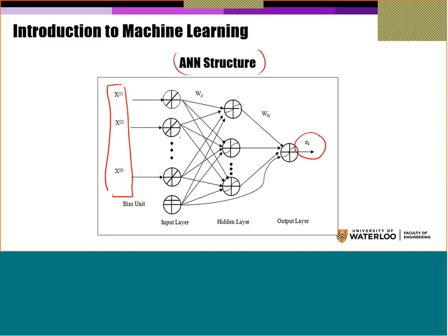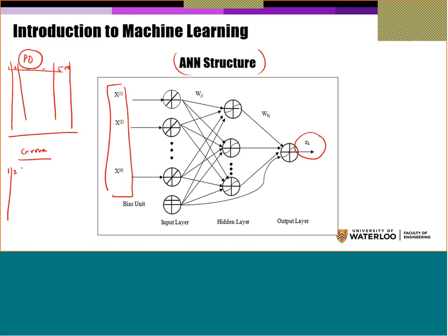In learning, what I do, let's say, back to my problem, I have a partial discharge problem where I have signals 1, 2, until 500. So I have 500 signals, all of them I collect when there is a partial discharge on the surface. And also I have a corona. A corona is a discharge not on the surface, but on the hardware, in the conductor itself. So again, I have 1, 2, until 500. I also have 500 signals. Okay, so let's say I will take 60-70% of this data, and I will train it using this.